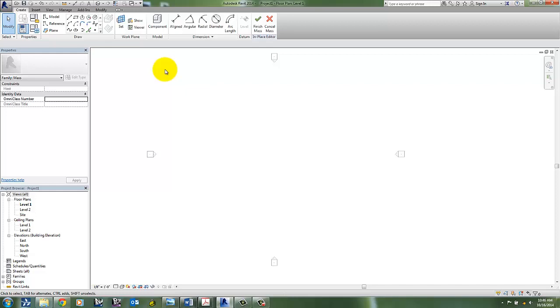All of those tools you can still make in a massing view, but massing has to be a lot more flexible, a lot more editable than something very strict like the modeling tools for the Family Editor. So you'll notice there's no extrusion, there's no sweep, there are no tools to tell Revit to create those forms. The way that you draw your lines and tell it to create forms, Revit is going to try to guess what you're trying to tell it to do.